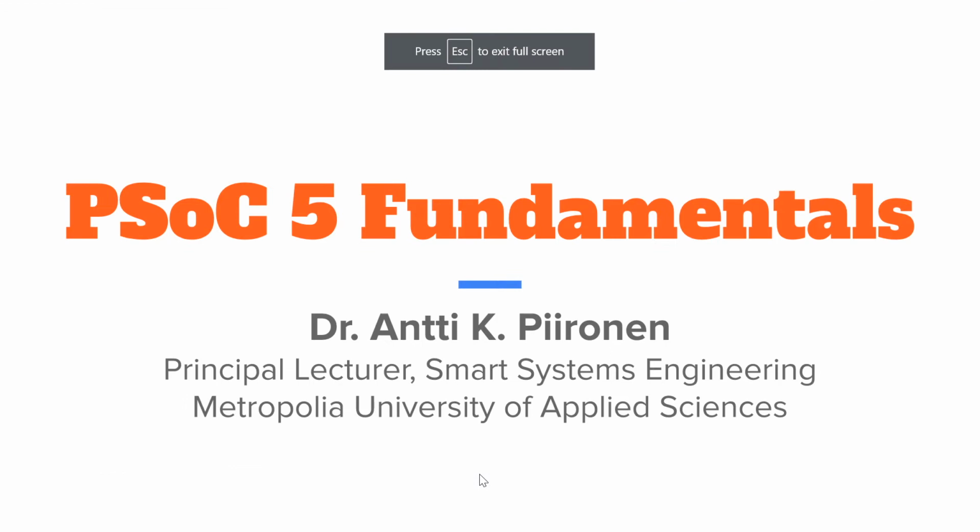slideshow, and so practically this is the programmable system of chips. So there are different generations of programmable systems. PSoC1 is based on an 8-bit M8C core, and then the PSoC3 is an 8051 processor, old-fashioned, and then this PSoC5 is actually an ARM 32-bit core. I think it was an M0 core, but anyways, it's a quite powerful processor already.